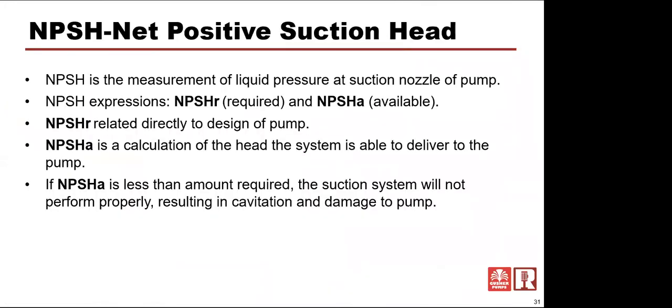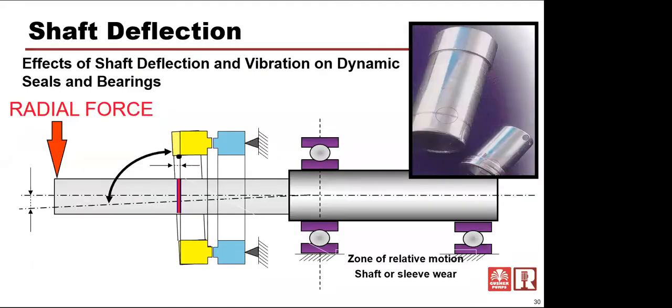Oh, I had a question. Sorry, go ahead. I'm trying to catch you right as you're turning the corner here. We can go back to that slide with the deflection and the radial force. So over time, as we're looking at pumps in this application where they're getting this excessive radial force, we assume that eventually these bearings are going to also show wear, and regardless of a new seal or a new shaft, if these bearings aren't addressed, you could continue to see reduced seal life just because the bearings are wearing out as well.